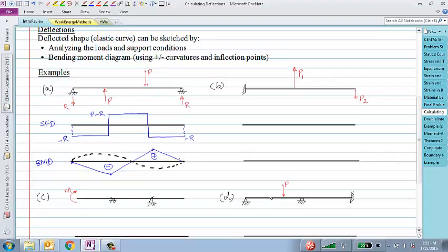Any questions on this example? So this is again just trying to intuitively understand how we can quickly judge what the shear force, bending moment diagram and deflected shapes would be like for simple structures. You obviously cannot generalize this technique for more complicated structures with complicated loading. But once you do have a bending moment diagram for complicated structures, you can draw approximate deflected shapes like that.